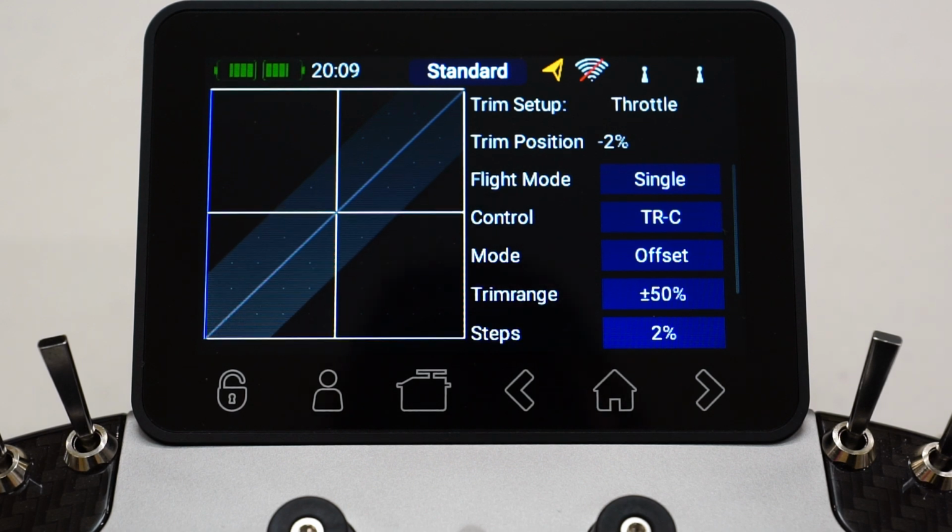So that was handy in that example where you go fly, you deploy your flaps, and say my flap half position was a different flight mode, and I'd trim the pitch of the aircraft in that flight mode. And then when I flick out of that flight mode, say go to my normal flying position with 0 flaps, the trim's a different trim. And once you set it in the transmitter, then you don't have to worry about it. The flight mode automatically switches in a different trim.